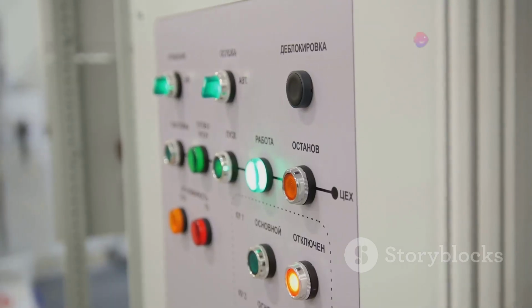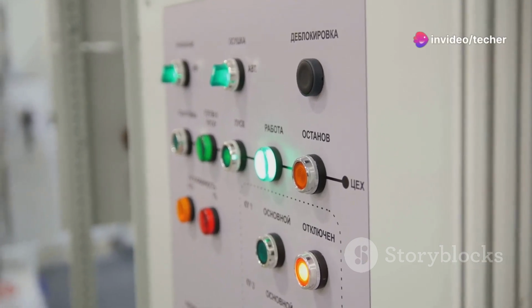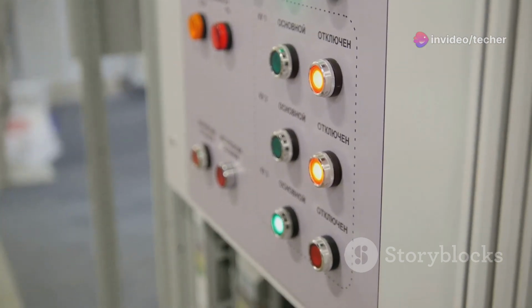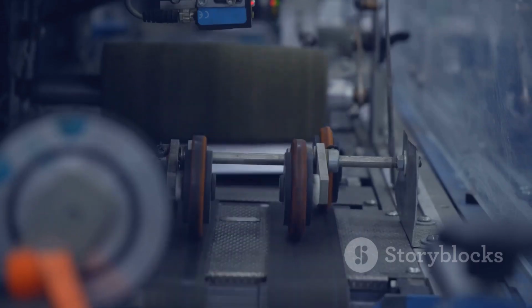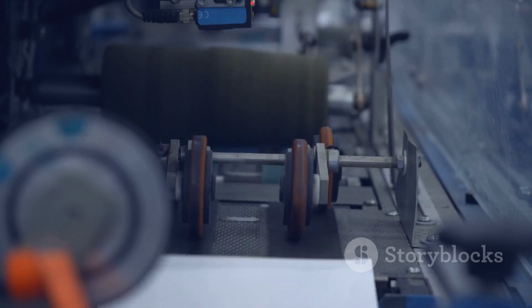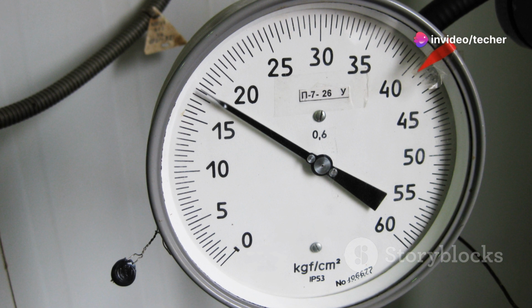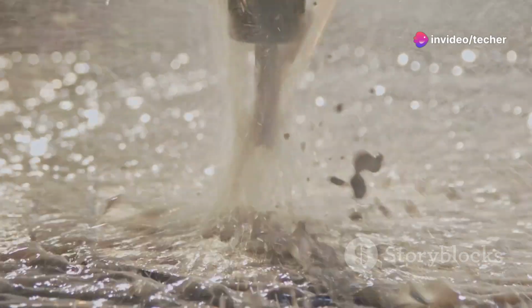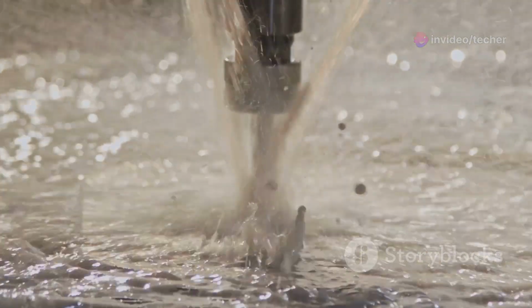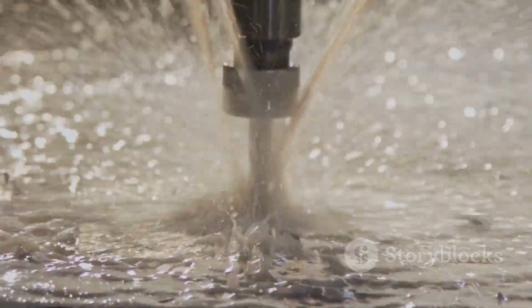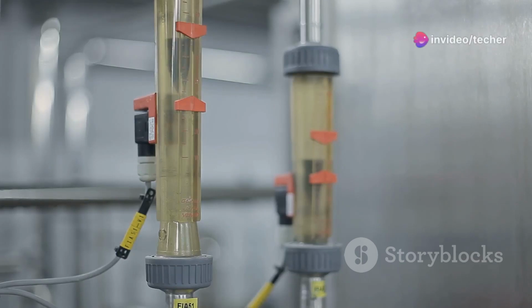Digital pressure sensors are often preferred in industrial automation due to their ability to provide clear-cut on-off signals based on pressure thresholds. These signals can be used to trigger events, activate alarms, or control actuators such as valves and pumps. For instance, a digital pressure sensor can be used to monitor the pressure in a pipeline. If the pressure exceeds a predetermined safety limit, the sensor triggers an alarm and shuts off a valve to prevent potential damage or hazards. Similarly, a pressure sensor can regulate the flow of liquids in a tank by controlling a pump based on the measured pressure level.